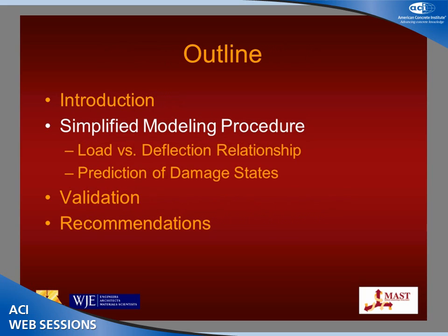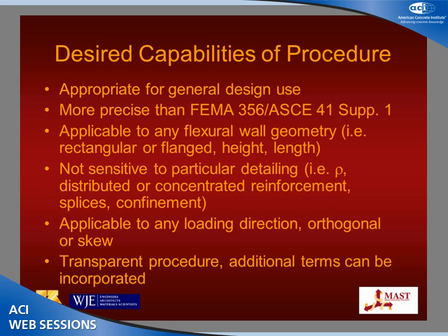So the simplified modeling procedure I developed includes both a load versus deflection relationship for pushover analysis and a framework for the prediction of the damage states. Our desired capabilities of the procedure were, number one, it needed to be appropriate for general design use, so it could not involve abaqus. But we wanted something that was more precise than the FEMA 356 and ASCE 41 model.